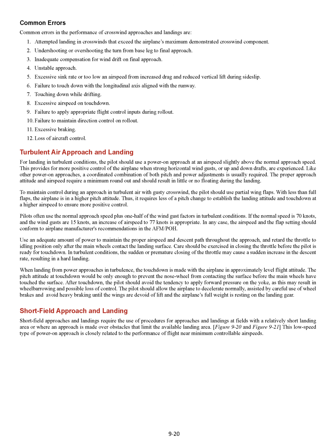the AFM/POH. Use an adequate amount of power to maintain the proper airspeed and descent path throughout the approach, and retard the throttle to idling position only after the main wheels contact the landing surface. Care should be exercised in closing the throttle before the pilot is ready for touchdown. In turbulent conditions, the sudden or premature closing of the throttle may cause a sudden increase in the descent rate, resulting in a hard landing. When landing from power approaches in turbulence, the touchdown is made with the airplane in approximately level flight attitude.